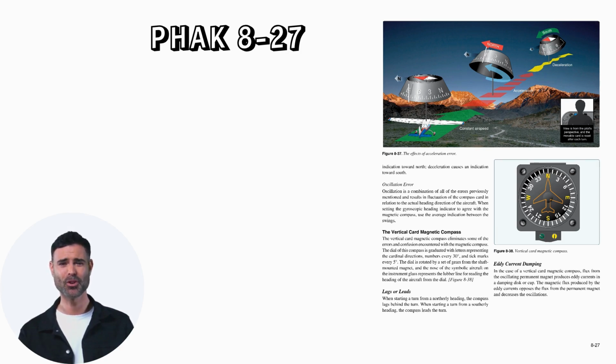When starting a turn from a northerly heading, the compass lags behind the turn. When starting a turn from a southerly heading, the compass leads the turn. Eddy current damping. In the case of a vertical card magnetic compass, flux from the oscillating permanent magnet produces eddy currents in a damping disc or cup. The magnetic flux produced by the eddy currents opposes the flux from the permanent magnet and decreases the oscillations.